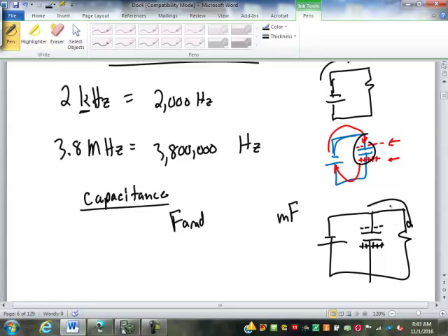So if you have a power surge or a power dip, let's say you have a sudden dip in power. Well, if this voltage falls below 120 volts, this capacitor will discharge, and there'll still be a small dip in power, but the capacitor will discharge to compensate slightly, so whatever you're trying to operate doesn't dip quite as much. Same with a power surge. There's a power surge, and all of a sudden this shoots up to like 150 volts or whatever.